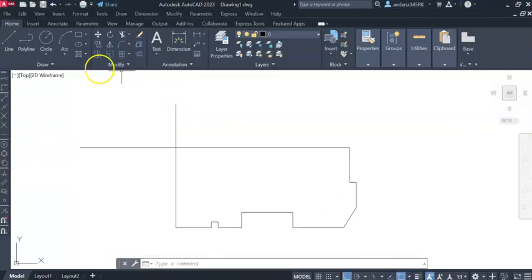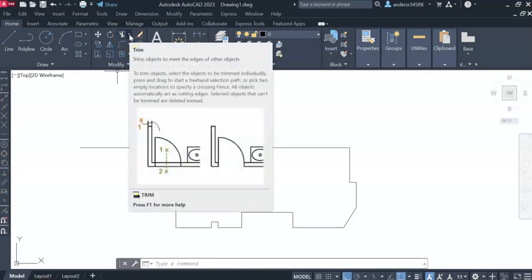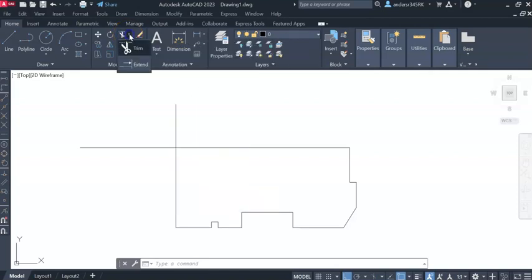Okay, right. So there's my trim, my scissors. I go to trim. Now you see there's a little arrow there. There's a drop down box. See, if I hit the drop down there, trim and extend are opposite commands. The one cuts it off, the one makes it longer. So what AutoCAD does, it groups similar commands with each other. Okay, if I just clear that.